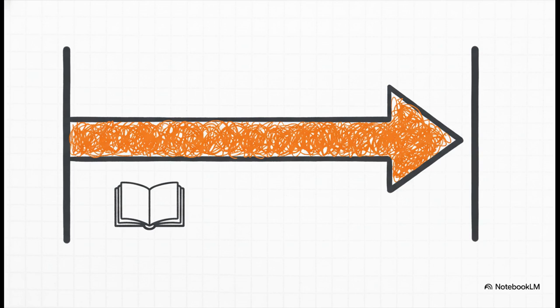Okay, rule number 1. This is the most fundamental of them all. Direction. The logical flow always, and I mean always, moves from that left power rail across all the conditions on the rung over to the right rail. Just think of it like reading a book. It only makes sense in one direction.